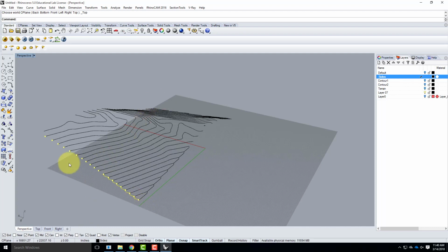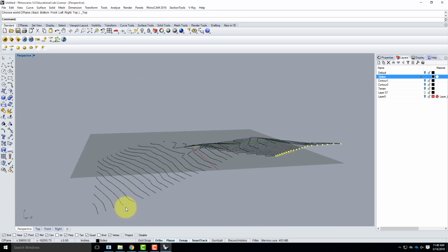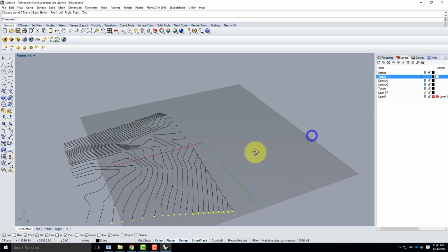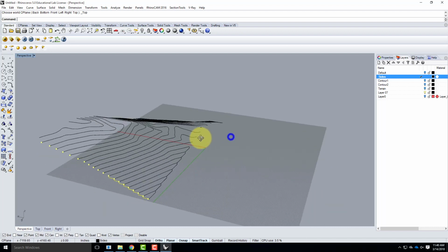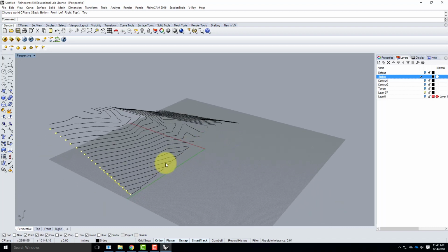So I asked you last class, yeah, RJ? You could technically do one C-plane and then do it for both sides. True, you can. So when I had the C-plane vertically here, I could technically be drawing along this back set. I find that you sometimes can get out of whack because your drawing plane, even though it's parallel to where you're trying to draw, is not actually in the same plane that you're trying to draw. So you're less likely to have errors if you actually move the C-plane. Okay. You can technically get away with it.